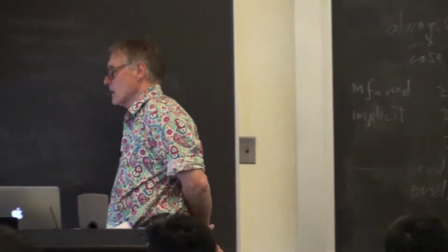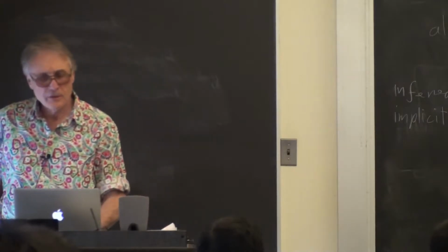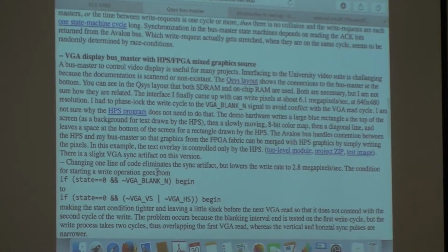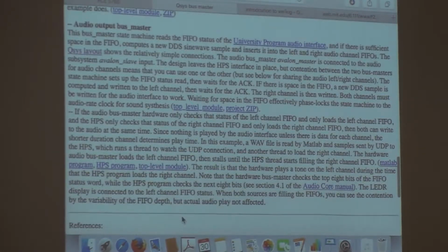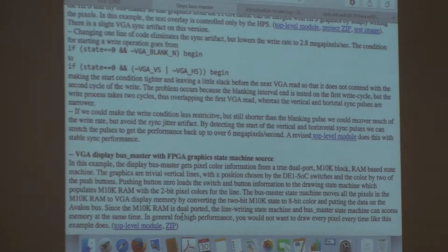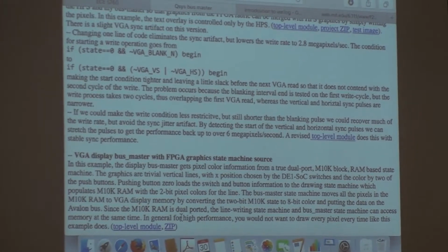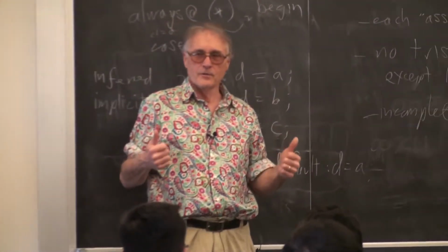So the plan now is to talk a little bit more about Verilog and then go back and pick up some material on bus masters. And what I'm going to do is to use the VGA display bus master example, since that's relevant for Lab 2, and also then talk about the audio output bus master, which is more complete because it does a complete read-write cycle to read a FIFO state, write the FIFO, read another FIFO, and if there's data, read the data. So it's doing a bunch of interlocked operations. That'll also get us right down to the nitty-gritty Verilog level.